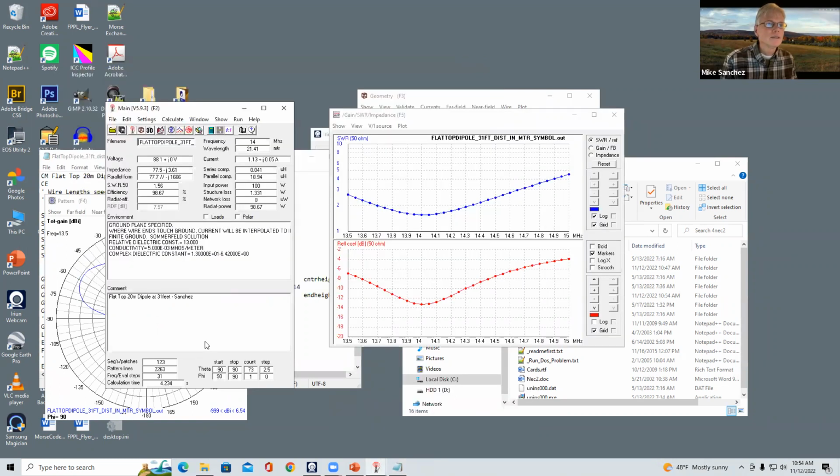And the minimum is sort of flat between 14 and 14.05. Obviously you wouldn't be too worried about this if you're building the antenna, but I do think that the previous minimum was more centered on 14. It was actually the increment below 14 was the same as the increment at 14. So we've shifted it up just a wee bit, but I think really if we were to see the phase angle of the reflected, that's where it would come in.